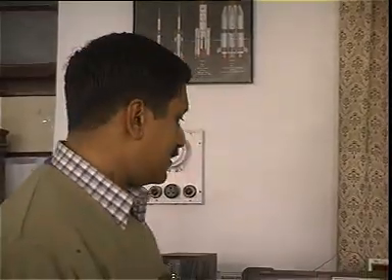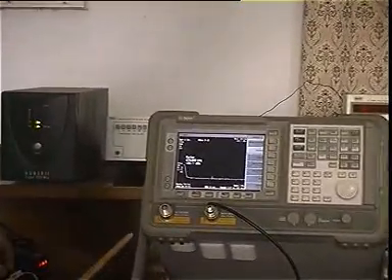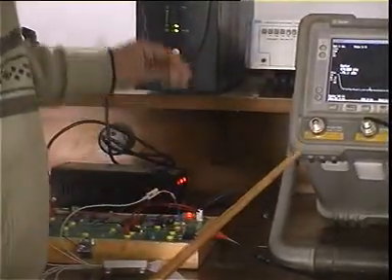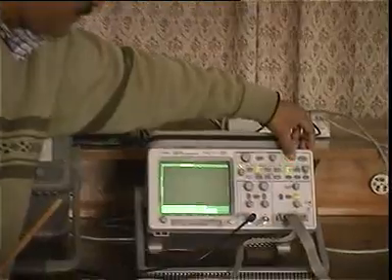So here, this is an example of what we call binary frequency shift keying. That is, I have only 0 and 1. I use one frequency to transmit a 0. I use another carrier frequency to transmit a binary 1. So here, let us look at the waveform now. Remember, sine 1 was 2 megahertz, sine 2 is 1 megahertz. So I am going to use 2 megahertz to transmit a 0 or a 1 and 1 megahertz to transmit the other bit. So here I am going to transmit by FSK.